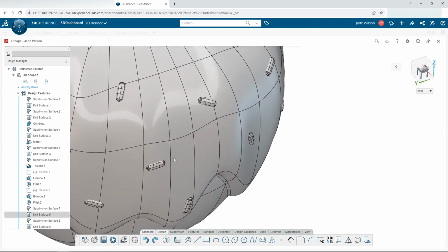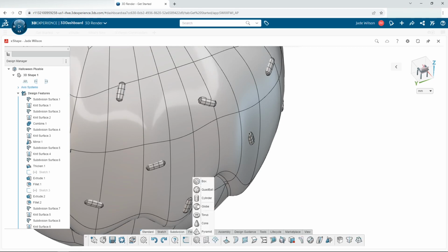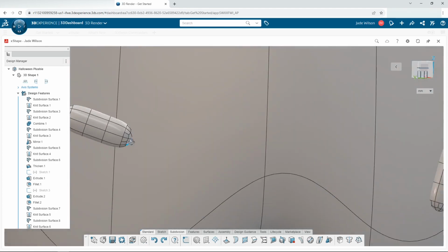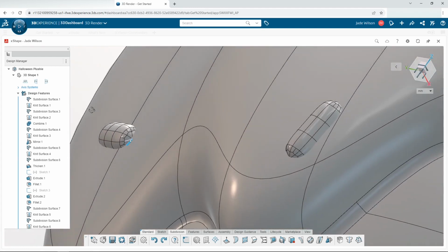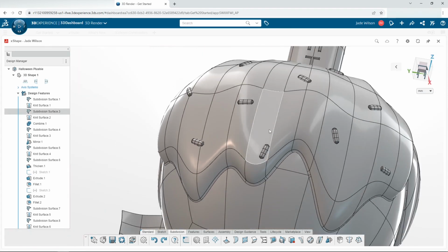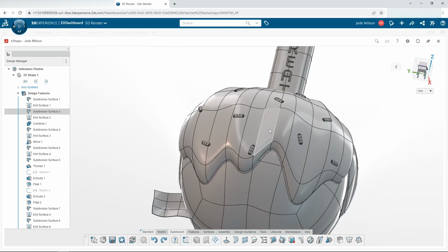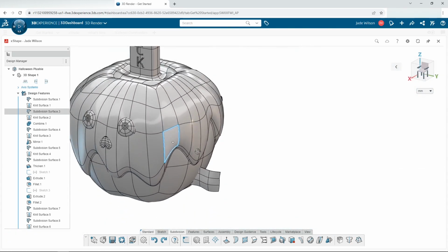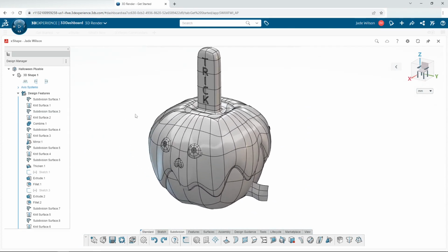The sprinkles would be another stitched element to the plush toy. They were created from one cylinder shape, which was stretched and squished into these sprinkles, and then copy and pasted to place onto the treat side of the apple. You can see when I zoom into this one that the cylinder shape was dragged into the apple body to its halfway point like this. Again, these were all kept as separate bodies to make it easier for me to apply appearances to them in SOLIDWORKS. Otherwise, I would have had to select all of the mesh faces individually rather than solid bodies.